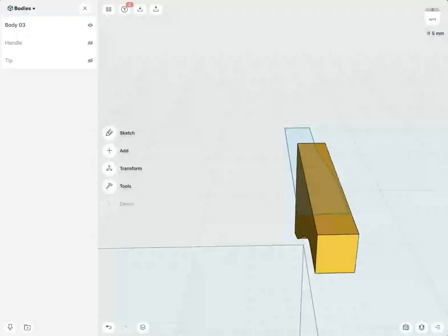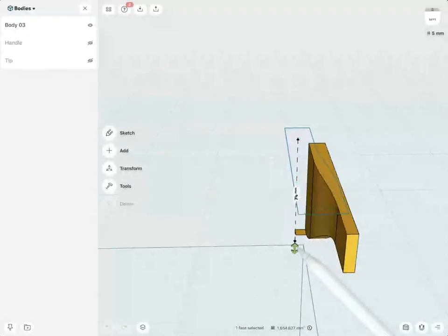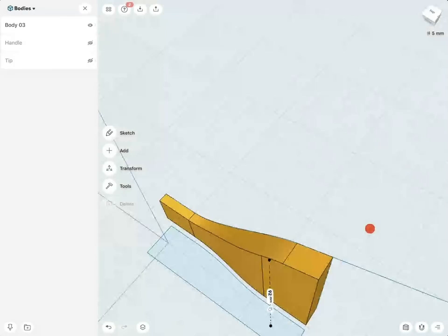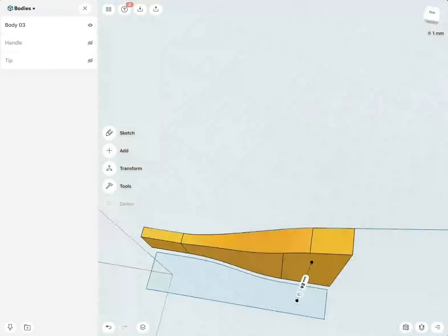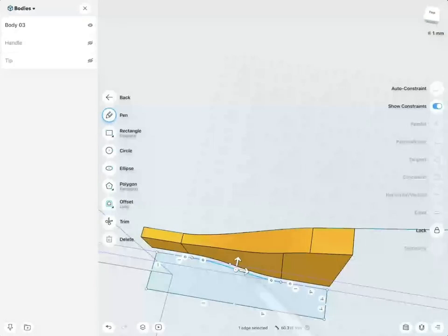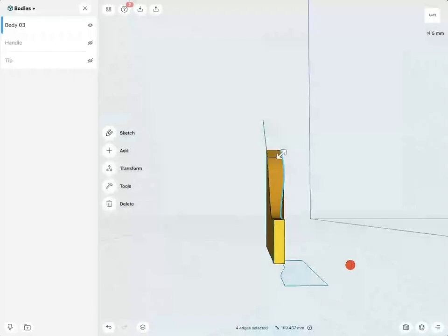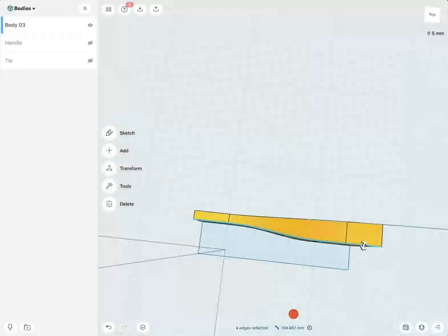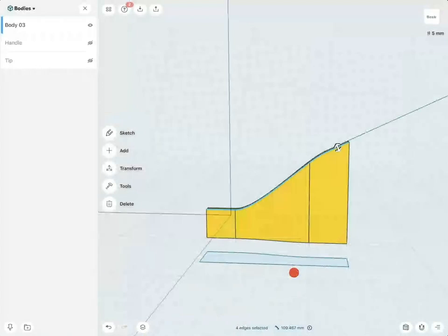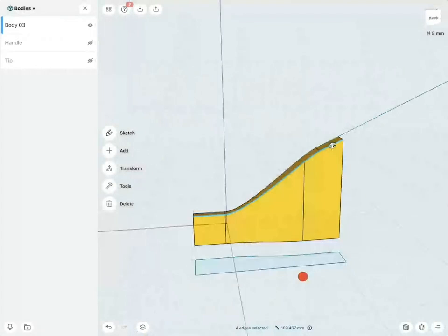And then I cut through my first extrusion. And you see, based on this shape and how I have these profiles drawn in 2D, I will then create a representation of this in 3D. So this lines up and this lines up. Let's see, very, very easy.